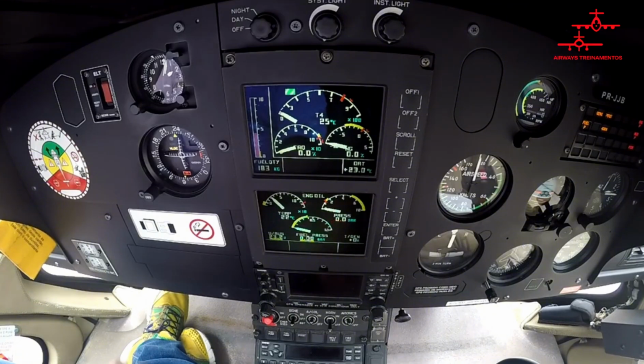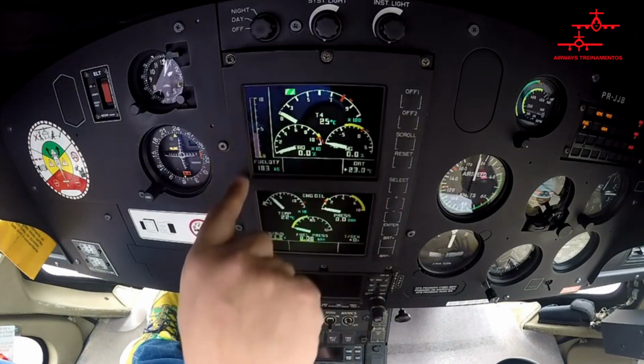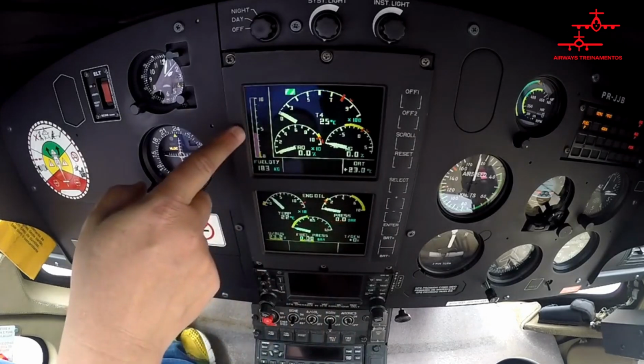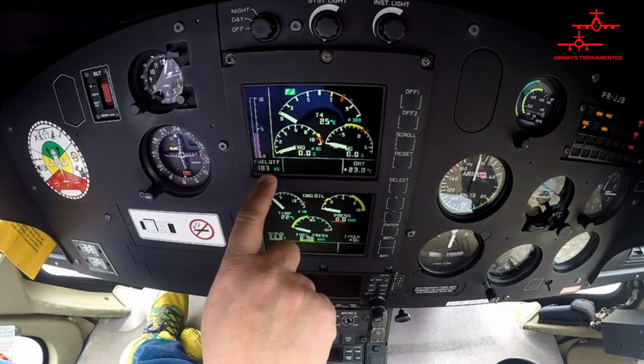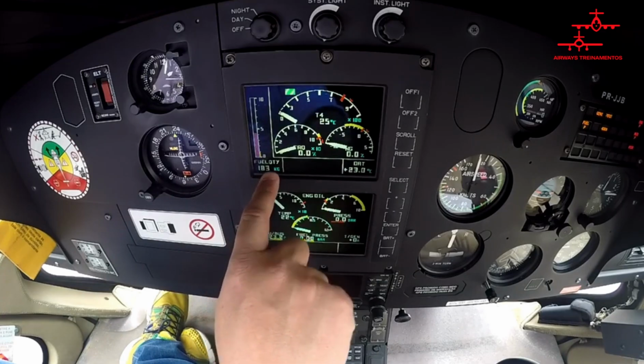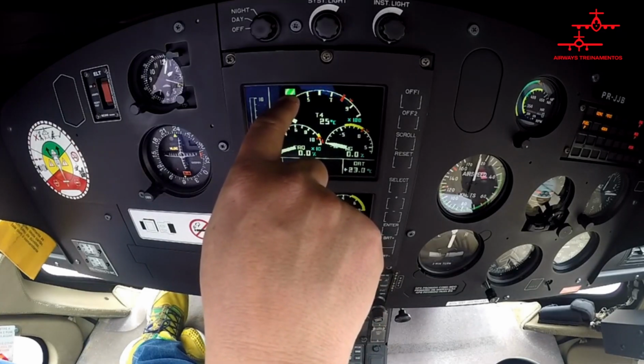And this VMD, at the top we have the fuel indication here, the flight range, pink, which is the amount of fuel inside the tank. But the pilot also has digital information down here at the bottom. Here we have the bleed indication, right? This green and white means that the engine bleed is open.